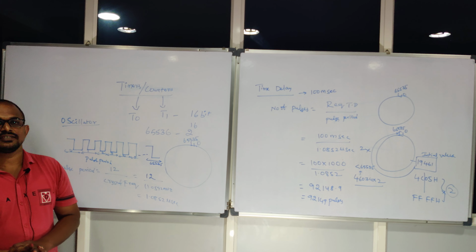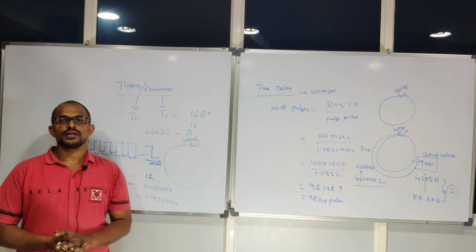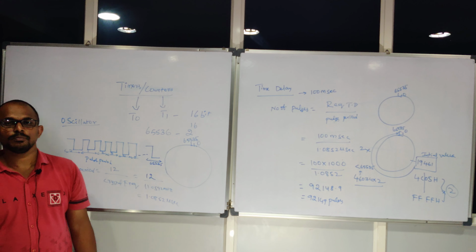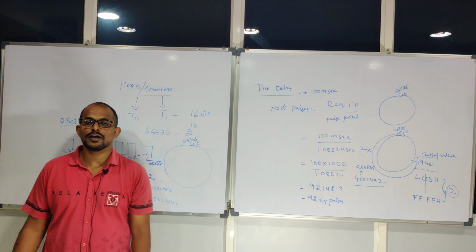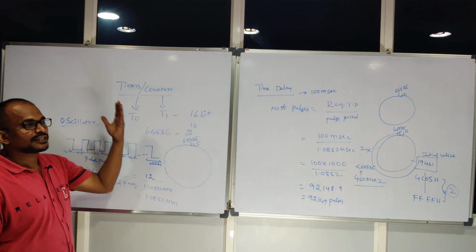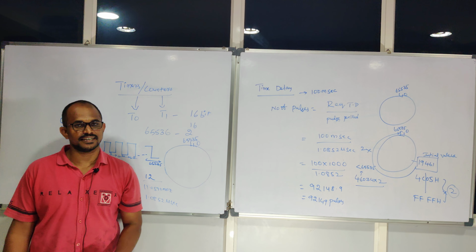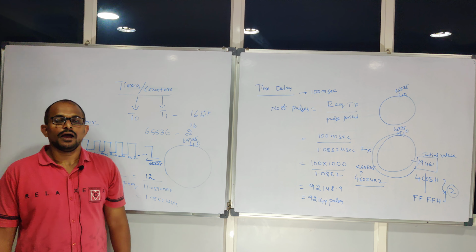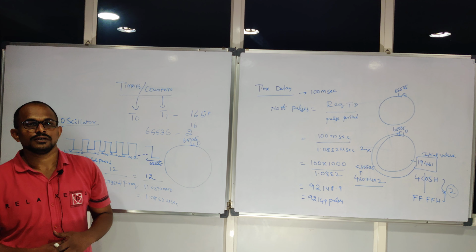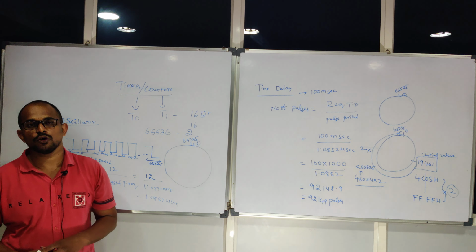If you have the basic idea about timer functionality and their uses, you can easily understand the next level microcontrollers like ARM controllers, STM32. For any microcontroller, timers are easy to understand. So basically your timers functionality is very clear. Timers are used for delay generation in most cases, and counters are used for counting external pulses coming from sources like sensors or any button operations.